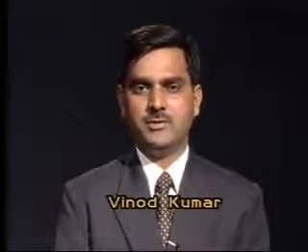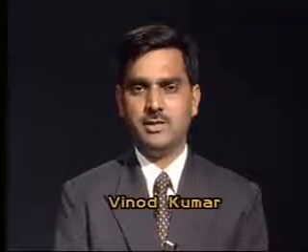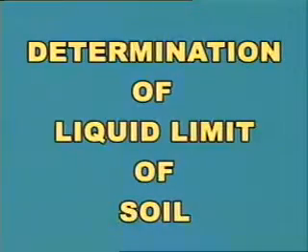Hello viewers, the liquid and plastic limits of soil depend on the amount and type of clay in a soil and form the basis for soil classification system. The liquid limit of a soil is the minimum water content at which the soil is still in liquid state, but has a small shearing strength against flowing, which can be measured by standard procedure. In this program, we shall demonstrate the determination of liquid limit of a given soil.